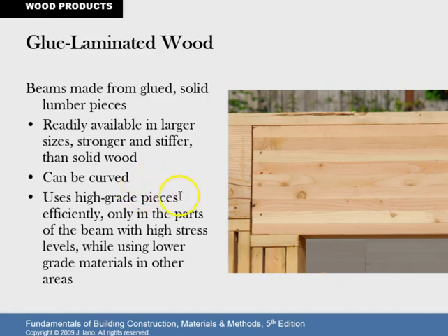And what do we say here? Uses high-grade pieces very efficiently, only in the parts of the beam with high stress levels, while using lower grade materials in other areas. So this is a very important point. I just had to read it to myself once. But it's basically saying, as I was just referring to, how a beam experiences compression and tension. It experiences compression up at its top face, and tension is greatest at its bottom face.